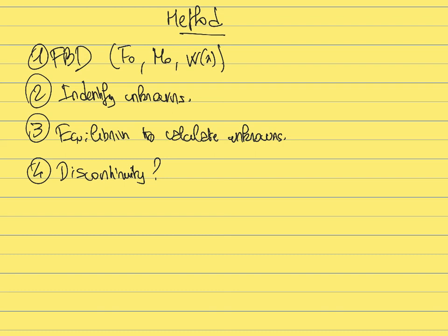And if there is, then the value of the concentrated force or the concentrated moment will be equal to the discontinuity of the internal shear or of the internal moment.